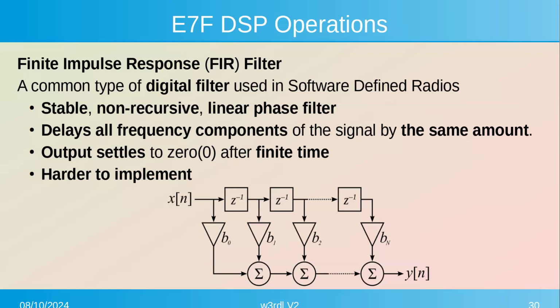And the more taps or stages you have, the better you can model the waveform. It's more accurate. Obviously, there's a longer time delay. So if you had 1,000 of them, in some cases they do, that's 1,000 samples delay before you're getting anything through there.